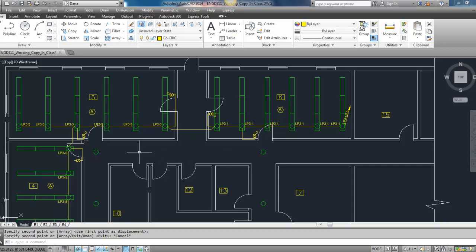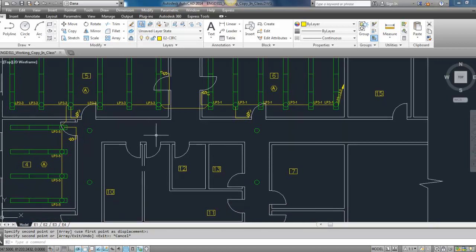I think that there's going to be not enough light. We'll have a little dark spot right about here if we were to place a light here. And we really don't want to place another light here because that creates an unsymmetrical layout for the hallway. So I'm actually going to divide this space up into 3. I'll draw another line, use my divide command, and let's see if this works here, divide it into 3 equal segments, and that's going to be the position of my other lights.